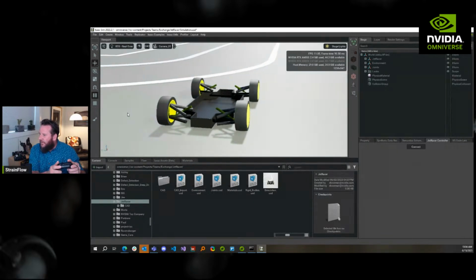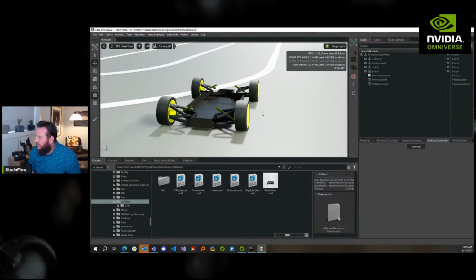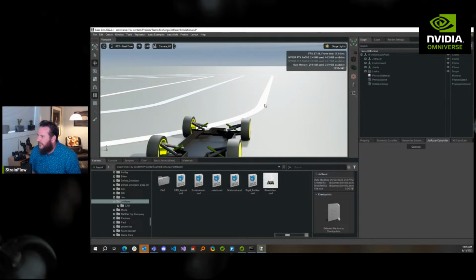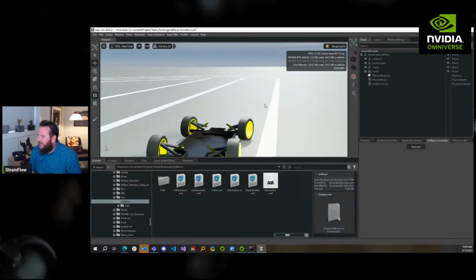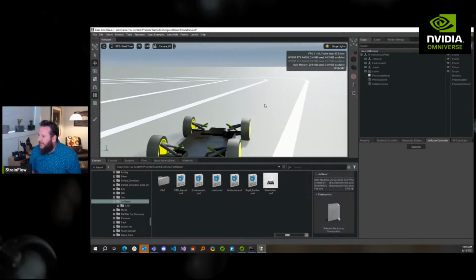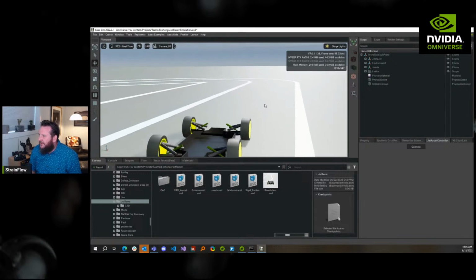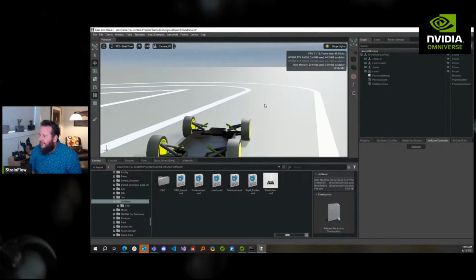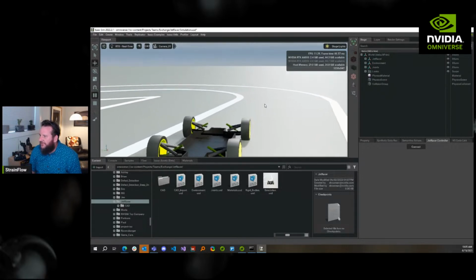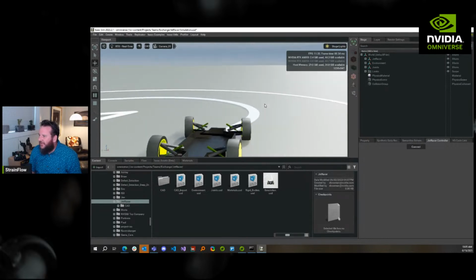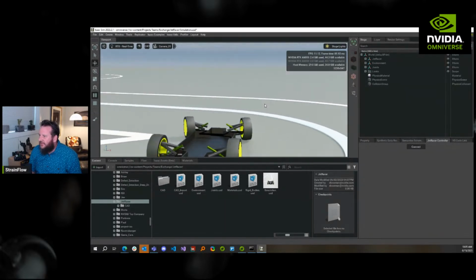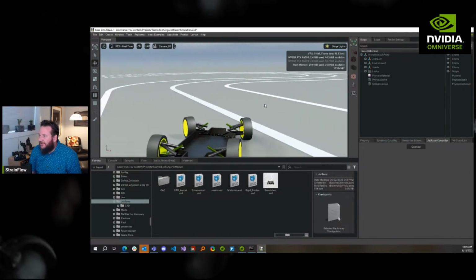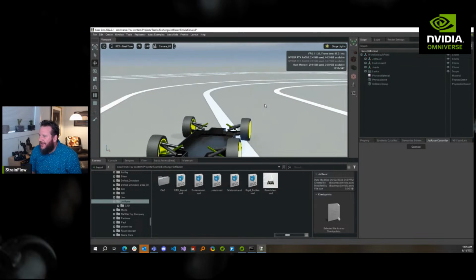Go back. Now, one thing you'll notice, it's a little bit bumpy, and that's something I'm going to have to debug a bit. But let's just drive around the track a little bit. And I've noticed if the bumping gets too big, then the physics simulation will actually fail, and Isaac Sim will crash. It's because if those joints get way out of bounds, I think the solver just gives up. So yeah, we're just driving. This is the track we want to teach this thing to drive around.